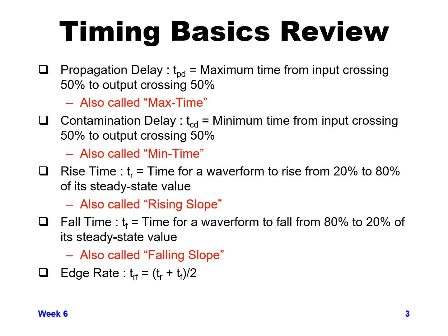While this is called propagation delay, it can also be called max time, and a lot of times I'll call it max time. At Intel, that's very common. Usually we don't use propagation delay. We'll call it max time for the maximum amount of time that it takes for the delay through the gate, 50% input to 50% output.